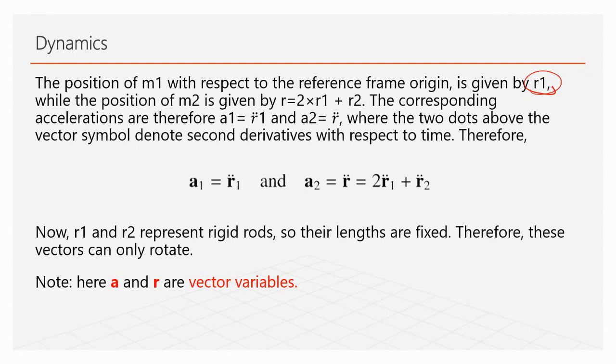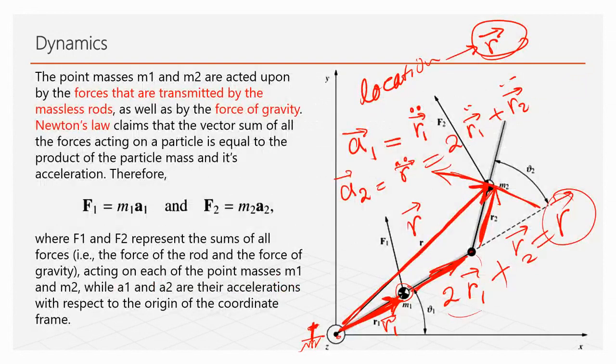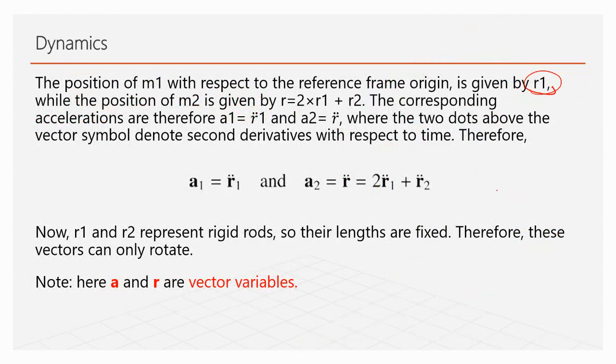But someone can come back to you someday in future and tell you, in another class somewhere else, okay, you remember this two-joint robot you used? Say yes. So I have a translational link in between, which means this length also changes. In that case, you have another parameter, D, or this chain, which will be added to this R1 here and makes everything different.